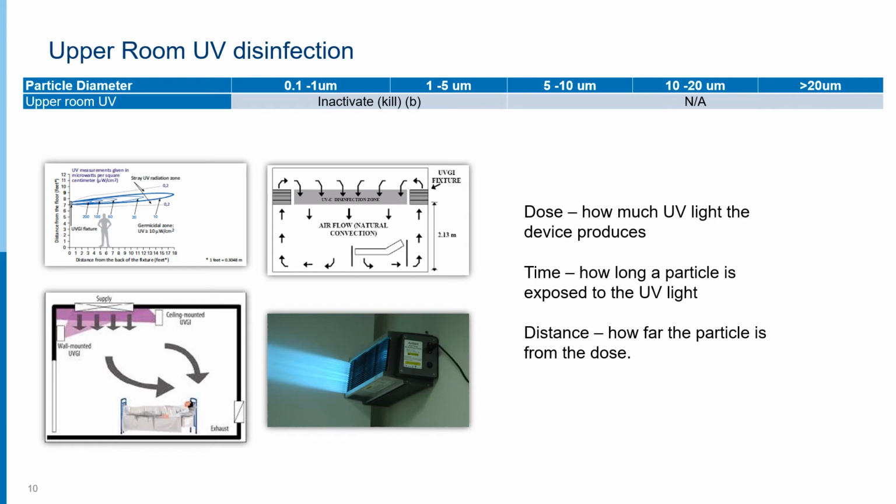This one for me is a bit frustrating. We know that upper room UV works. They've been shown to be effective in removing aerosols, so it has a lot of endorsement in the clinical literature. This is definitely a tool that we could be using. But the application of these is not as simple as air change rate or filter efficiency. It doesn't work in percentages. It takes some real design. And frankly, our industry literature, both domestically and internationally, is not strong in terms of vendor independent application guides. So a lot of building engineers, including myself, don't know how to apply it.